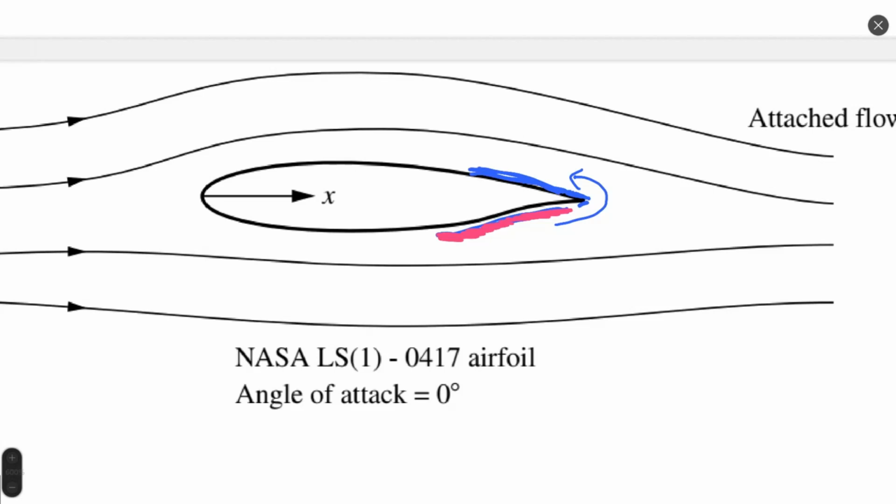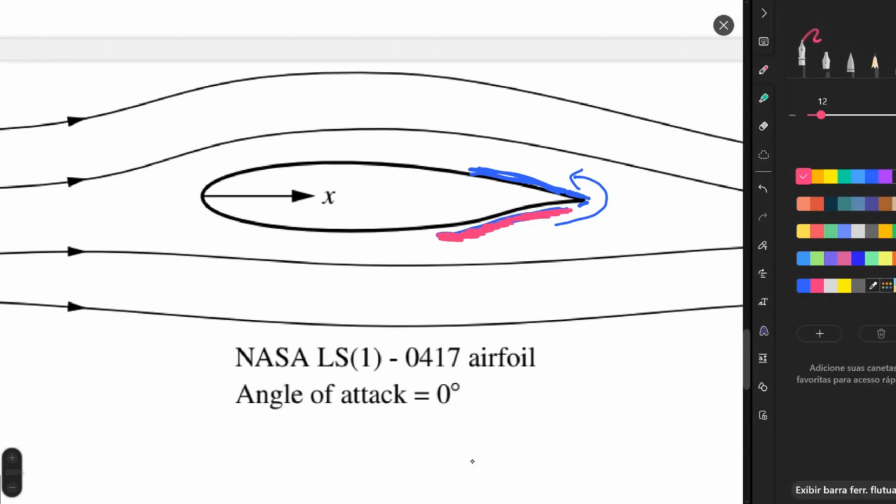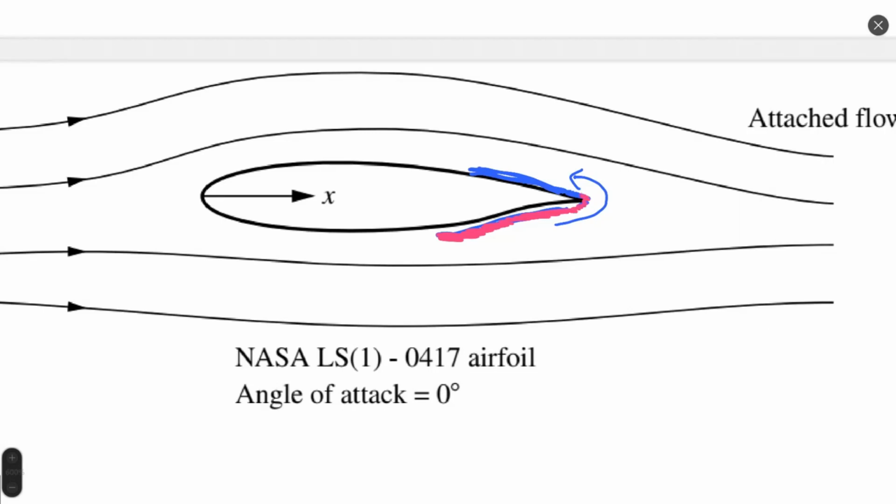And when this flow starts, not just the flow by itself, but a change of pressure happens inside the boundary layer. Since velocity is very small, change of pressure can happen quite easily. This pressure will start to rise on a small region here. It will start a small flow separation, and then this pressure rise with increase of angle of attack will spread further.